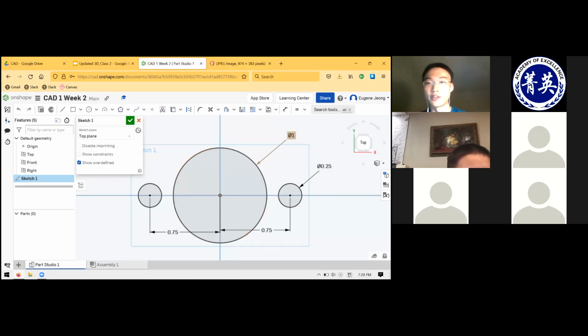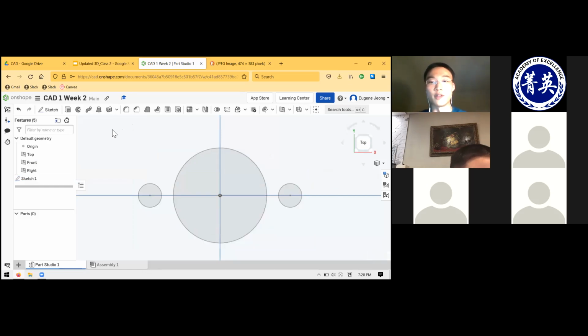Whenever you make a sketch, you can use these various tools to fully define it. And after you do that, then you'll really be free to start using these 3D tools, because making sure that the profiles, the shapes and regions that you're making are robust makes sure that your entire CAD model is robust and is less likely to break, because the most fundamental part of it, the very first thing you do, the sketches, are all solid.